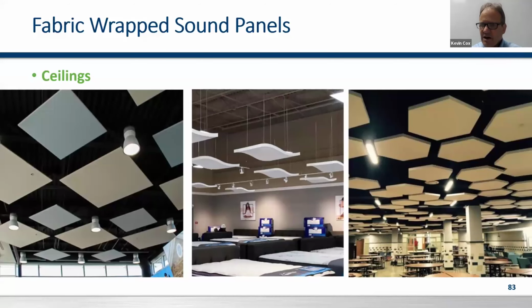So traditionally, acoustical clouds or acoustical absorptive clouds use a fabric wrap panel very similar to the ones that we'd put onto the wall with a chemically hardened edge, usually a matte fiberglass or semi-rigid fiberglass. A nice thing about these panels is that you get a two-pass benefit, so you can use less square footage. You can work with shapes and geometry a little more. So that first pass that would hit a face would be absorbed on that first pass, but anything that goes above that, that would hit structure, the back sides of these are also absorptive. So once again, you get that two-pass benefit, and you need a little bit less square footage to treat a space.